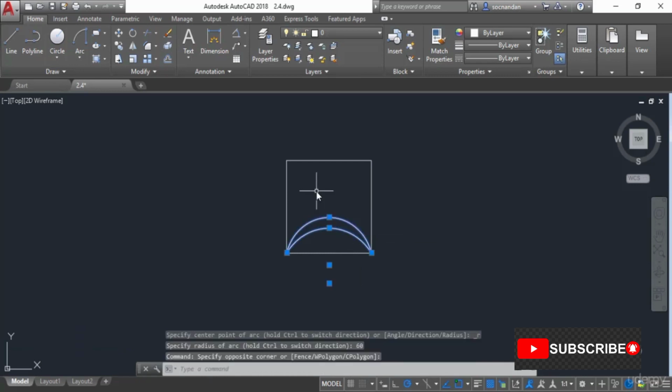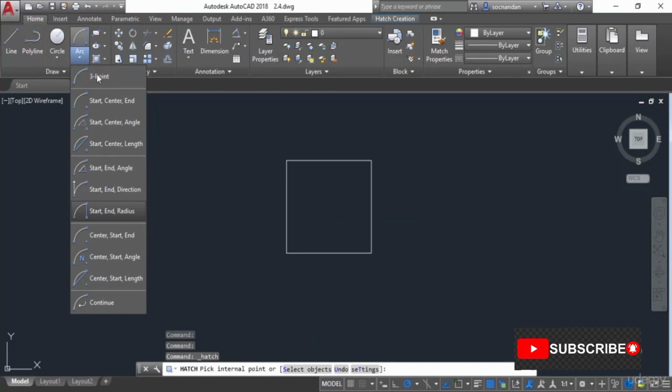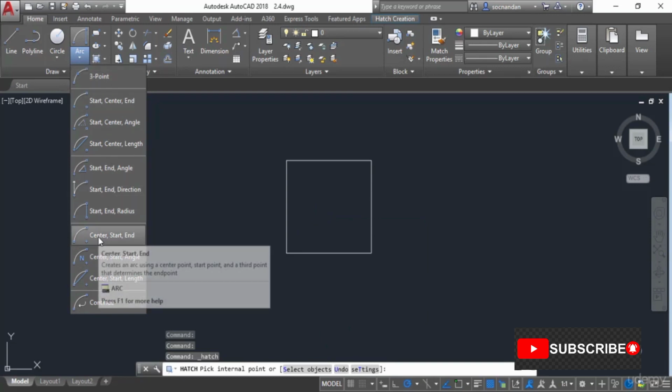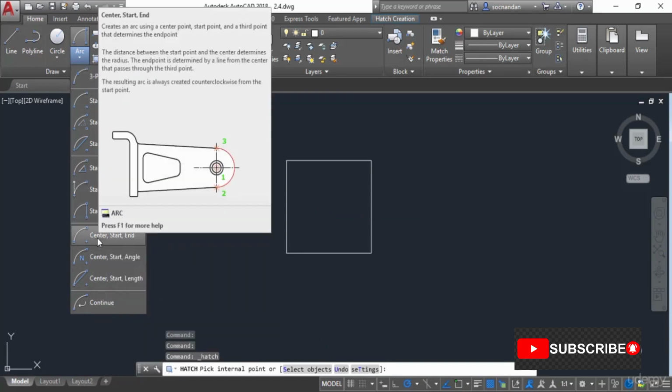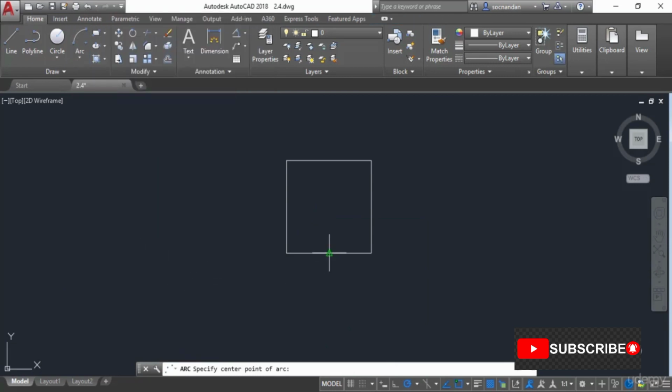So let's now erase both of these arcs and let's look at other options. So now we have this center, start and end. So obviously we need to first specify the center point, then start and then end. So let's click at this point. So that will be the center point. Now the start point, and choose this point as the start point.